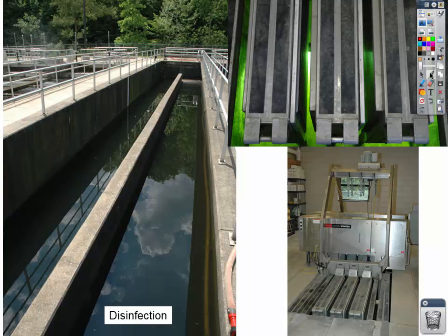So the way we disinfect is pretty much the same as the water treatment facility. We're going to disinfect using chlorine. It's somewhat controversial to continue to use chlorine, but it's effective. And as long as we allow that chlorine a chance to dilute or degas, it should be safe to put in the environment, and the EPA is checking at the end of the line here to make sure that chlorine levels are safe to put this water back into the environment.